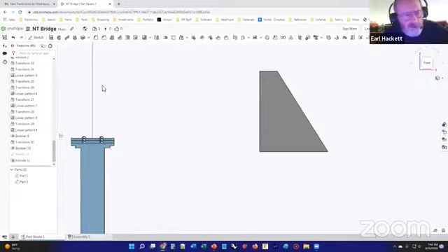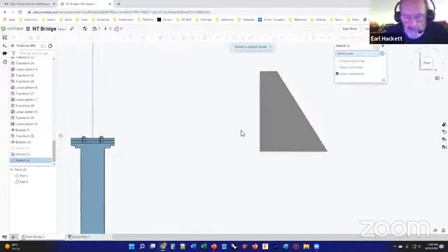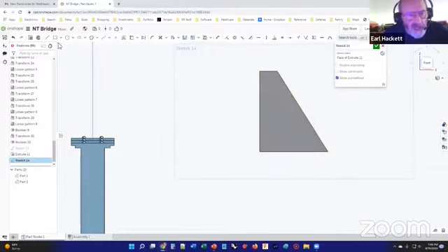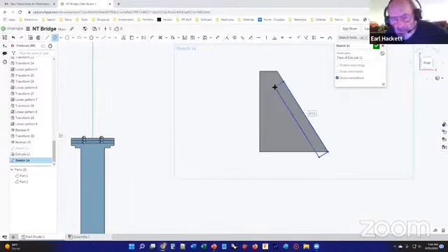We're going to use a tool that I haven't used before. We're going to sketch on this surface here, and we're going to use what they call an aligned rectangle. And this will create a rectangle at whatever angle you want. So we're going to start with this corner. We're going to come up, and I'm not going to go to that corner because if I do, it'll define that point. I don't want that defined yet, as you'll see in a minute. We'll go to here, and then we come down to here. Now this is, that's 1. Okay, so now we can define some things.